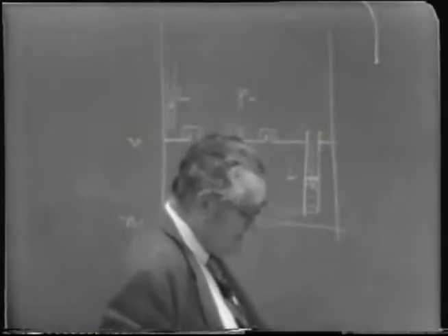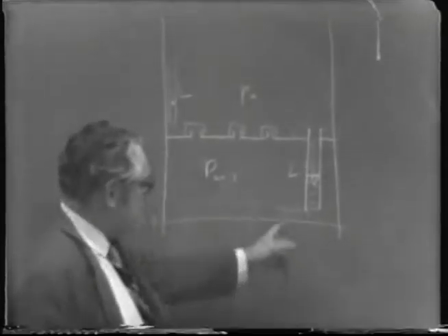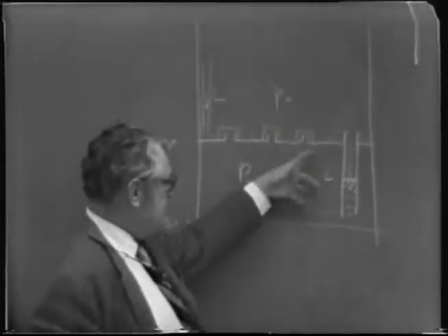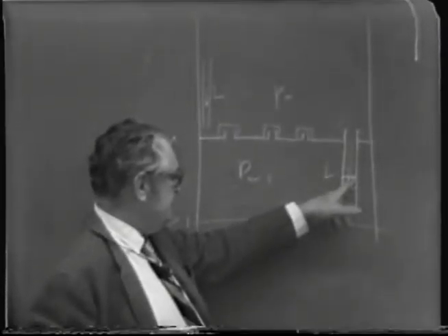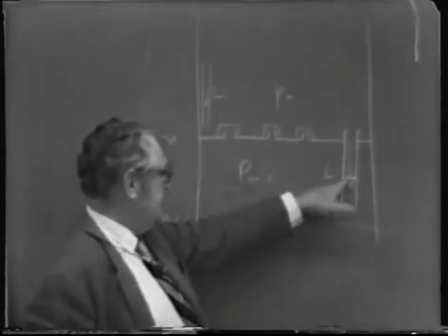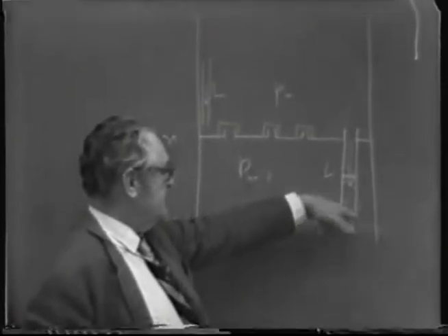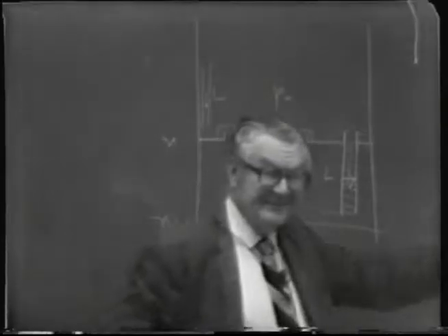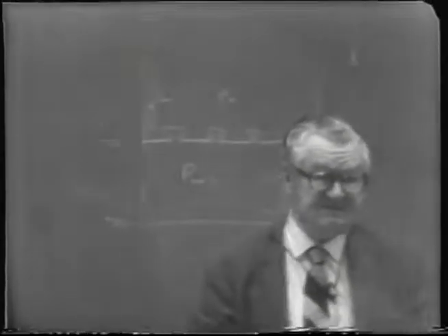And so as a kind of a practical measure, the practical rule is that the plate spacing should be checked so that the pressure drop is no more than enough to raise the liquid level up to about half of the available space.